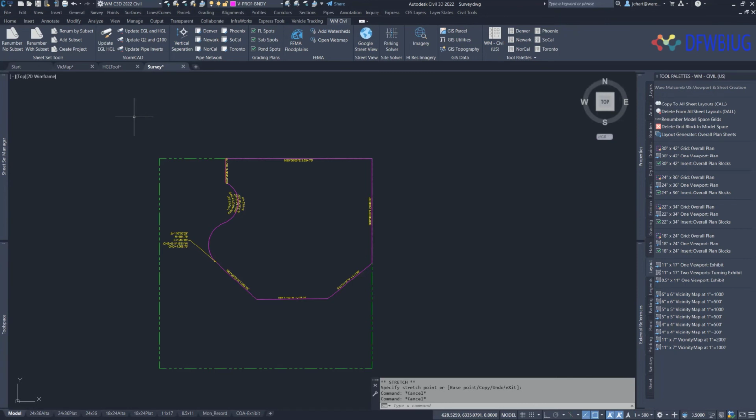What task are you seeing people automate with Dynamo the most? Well, for us, hydraulic analysis, taking 200 pipes from StormCAD and updating those HGLs, EGLs, inverts, and pipe sizes, being able to do that from a spreadsheet in about 20 seconds instead of 8 or 10 hours. And then somebody would fat finger and type the elevation wrong, and that's the one that the municipality would find. They always do. They only find the one area that you really mucked up.